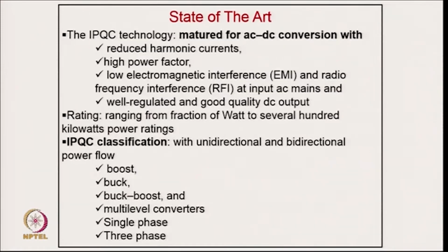Coming to the state of the art, the improved power quality converter technology is matured for AC/DC conversion with reduced harmonic currents, high power factor, low electromagnetic interference and radio frequency interference at input mains, and well regulated, good quality DC output, with ratings ranging from a fraction of a watt to several hundred kilowatts.